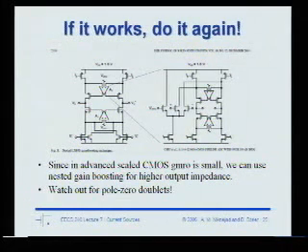Just the fields coupling from the output back to the input. Even though it's very small, it has loop gain because your forward loop has so much gain. Thermal feedback is another thing. One transistor gets hotter, and the threshold voltage of a transistor nearby changes. That's a parasitic feedback path. They're sitting on the same substrate.